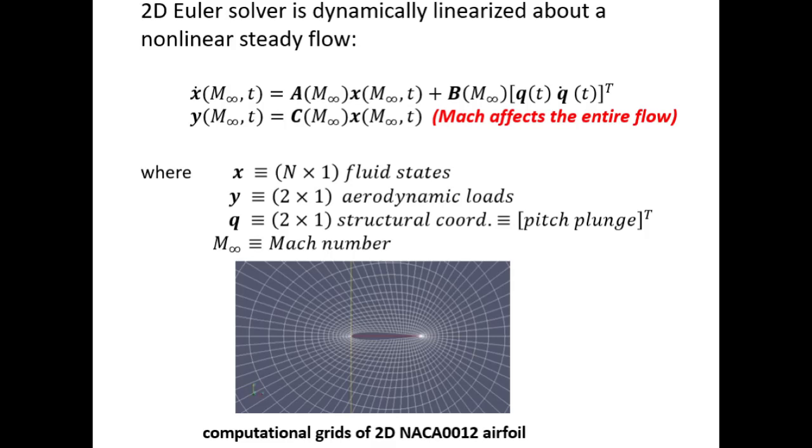As discussed earlier, the entire domain of the flow is affected by Mach number, which is a measure of compressibility of the air. Therefore, we are dealing with a global parameter variation that affects the entire flow domain. We can expect the first-order MEPs will not generate a vector space that is modally rich. We need the higher-order MEPs towards that end.